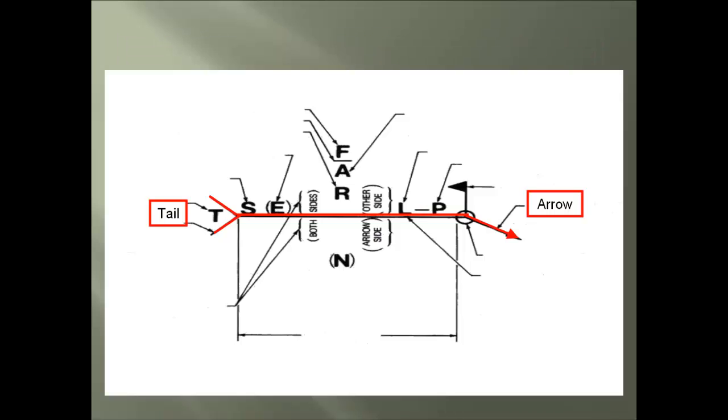Back at the weld symbol, we covered the actual body line, the arrow and tail, plus we see that there is the arrow side, which is on the bottom of the line, and the other side, which is found above the line. Now, we will cover notations of importance. There is a black flag shown here, and that represents field welding. And if there is no flag, that would mean it's welded in a shop.